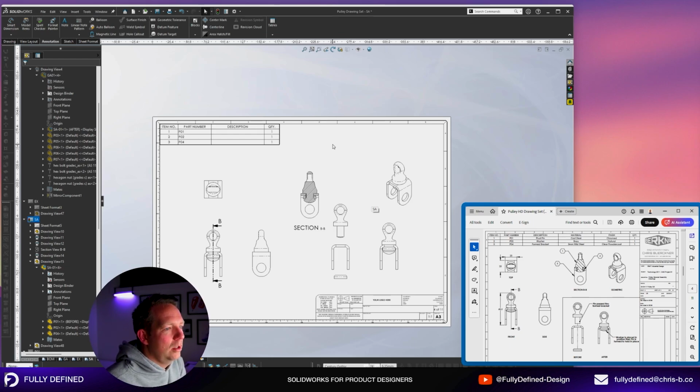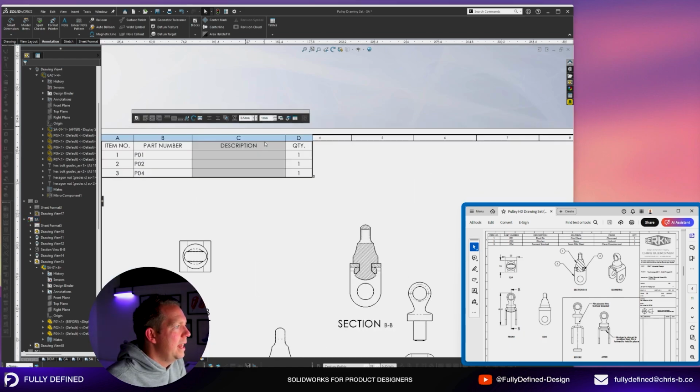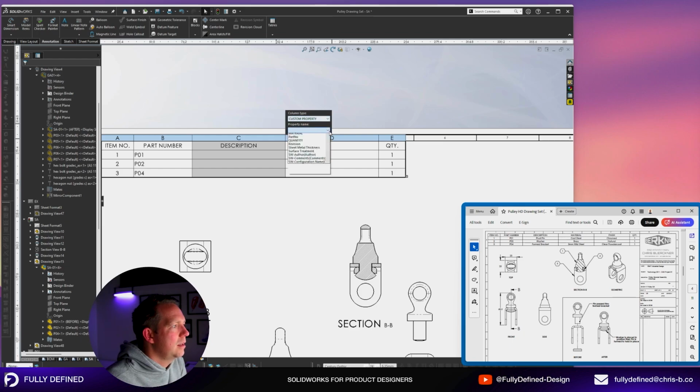We're going to add a column for material, and we're going to add a column for finish. To add a column, you right click on one of the headings of the column. So C, letter C, right click. I'm going to insert a column on the right, and I'm going to select the property.